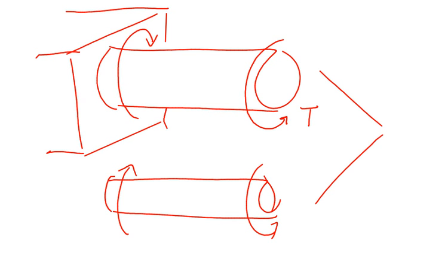Okay? And dynamic equilibrium simply means that the shaft is rotating at a constant rotational speed, right? It's got a constant angular velocity, if you will. So usually, in machinery, when you're talking about cars, the units we use are revolutions per minute, right? RPMs. So as long as the shaft is rotating at a constant RPM, then it's in dynamic equilibrium.